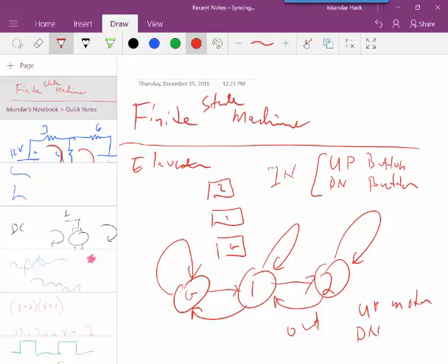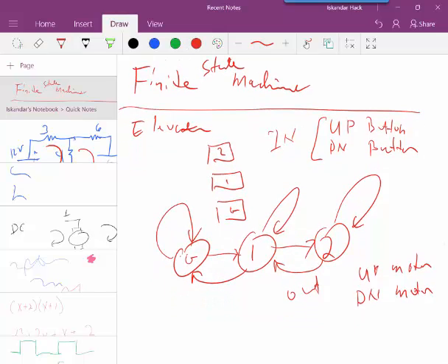Now, we could argue that there's 1 motor and we shift the transmission to go up or down, but for sake of keeping things simple, we're just going to simply say that we send a signal of up to the motor to tell it to go up. We send a signal to down to tell it to go down. And with 1 pulse, it only goes 1 floor. So this is a typical state machine with 3 states right there.